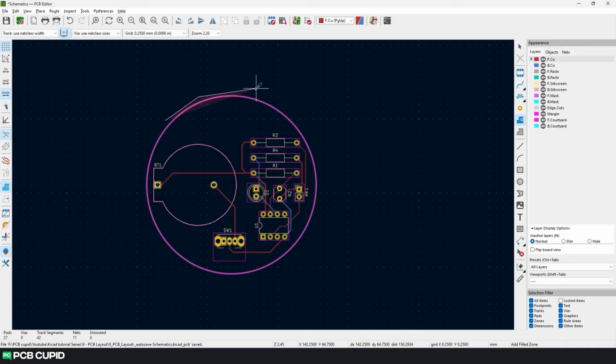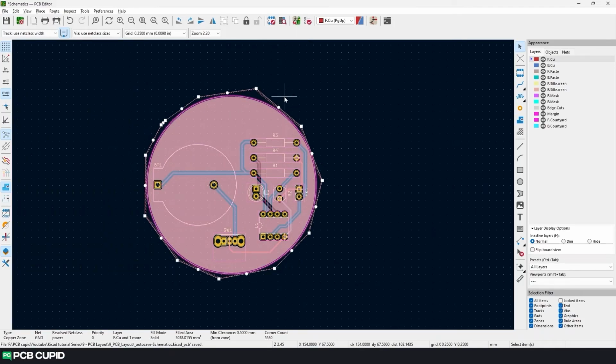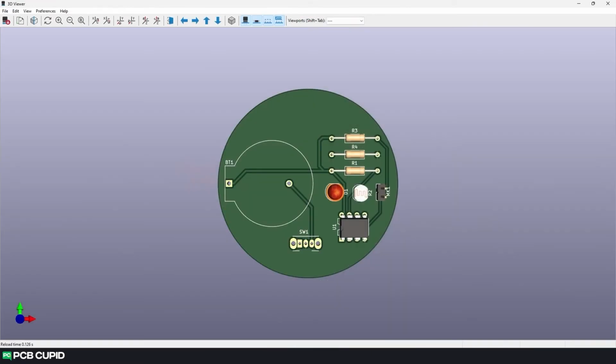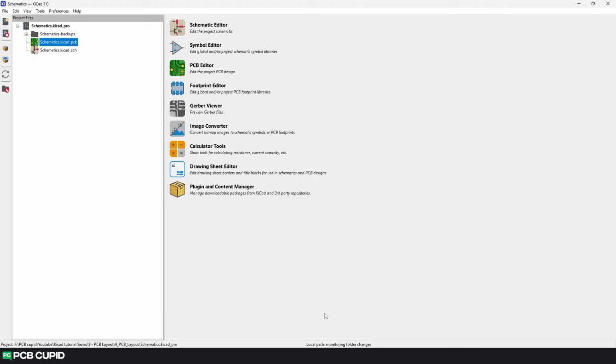Now the PCB design is perfect for manufacturing, and also it follows all the constraints that the fabrication plant needs. Personally, I do miss having graphics and branding elements on the PCB. So I'll show you how we can add a logo or custom graphics to the PCB. Go to the KiCad project window, then click on Image Converter.